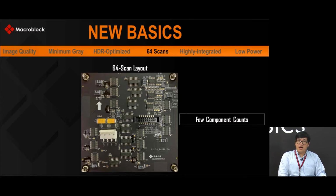First, the driver count will be half in 64 scans, and therefore the PCB design and layout will be flexible and clear. And sometimes you may need 36 scans design. On the other hand, the 64 scan LED driver will have the benefit of reducing the power consumption due to the fewer LED drivers used.